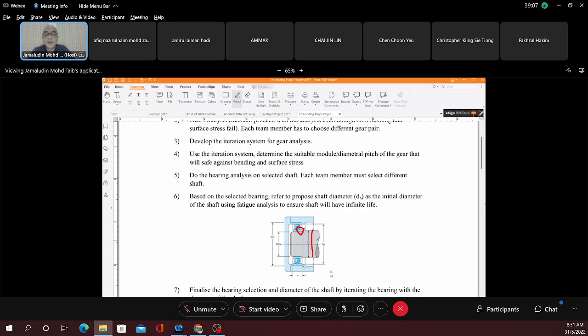This is going to be your first shaft. If you run the diameter, it is going to be an iteration process as well, because the shaft is d cubed. With the new calculator, you can iterate very fast. Bending is 32M divided by πd cubed. It is an iteration process, because Kf relies on the diameter and so on.